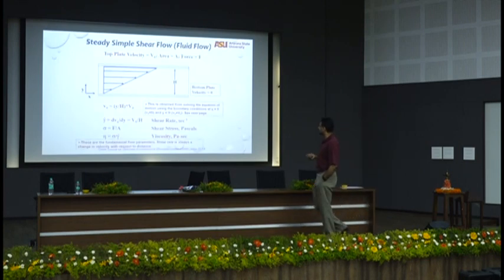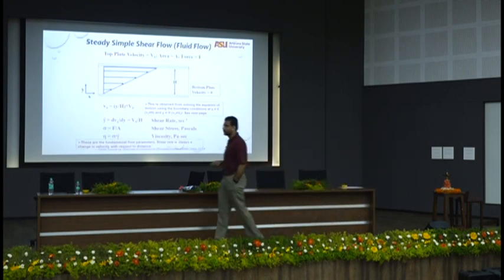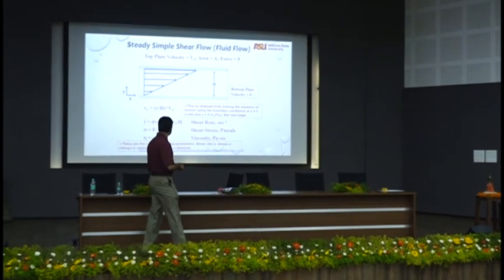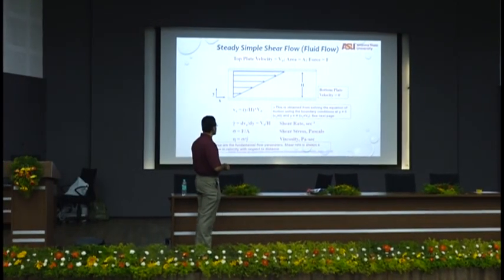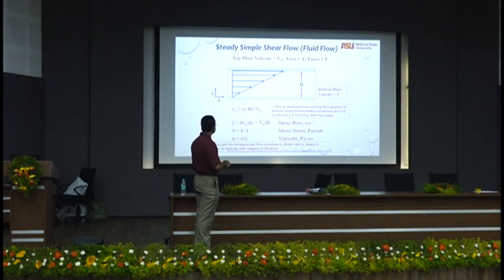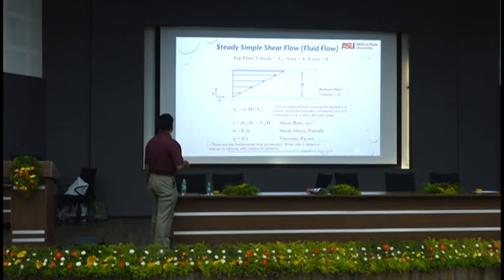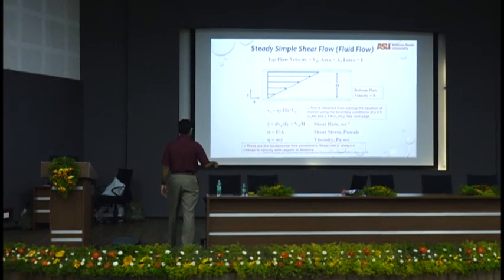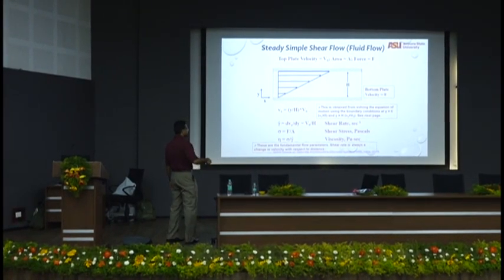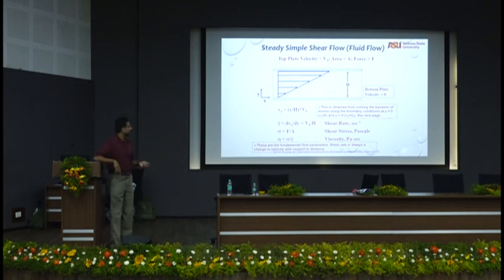And then you can do some math here. If you are interested in how the derivations are, you can look at it. So I'm assuming this layer to be not moving, this layer to be moving. Therefore, if I do an experiment in the lab, I will keep a stationary plate and I'll rotate the top plate, or I'll keep a stationary plate and I'll slide the top plate. That's how you do rheology experiments. So you will get viscosity as stress over strain rate, as opposed to stress over strain that you get for elasticity.